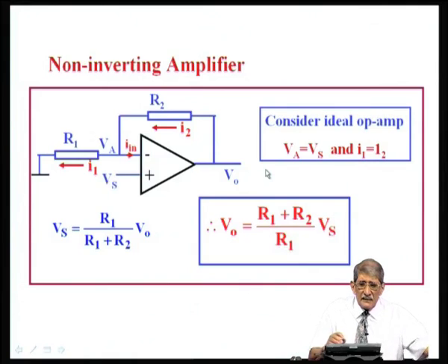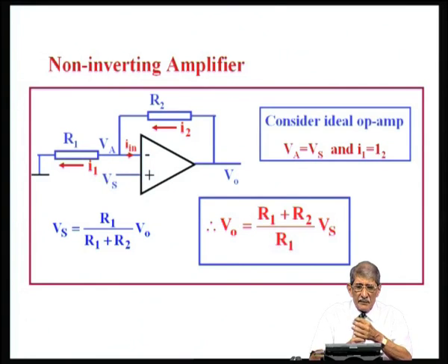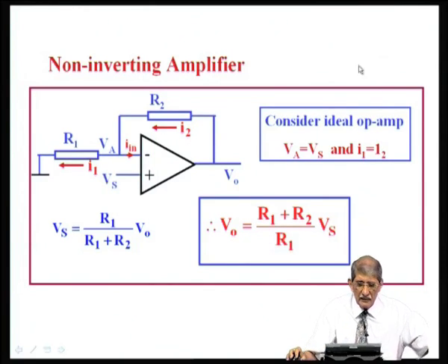In fact, this particular type of amplifier is very commonly used in the Wien bridge oscillator for amplitude stabilizing purposes, to realize the amplifier of gain 3. You have an RC combination and an amplifier of gain 3; you can precisely get this gain 3 for the Wien bridge oscillator by choosing this ratio as 3. This is very commonly used.